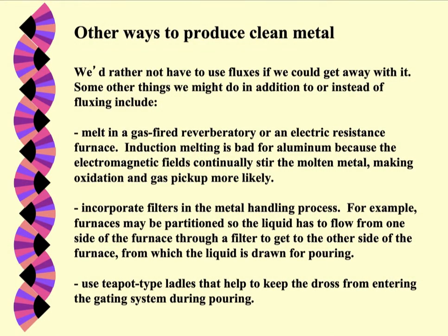So in industry, what we do is we use a reverberatory type furnace, which is essentially a big, almost like, looks like a swimming pool, or resistance furnace. So you have essentially what we have in the lab, a kiln with a crucible in the middle of it. They're just bigger in industry, okay? And then they don't lift off like that. They just stay put. So induction melting is bad because of the stirring.